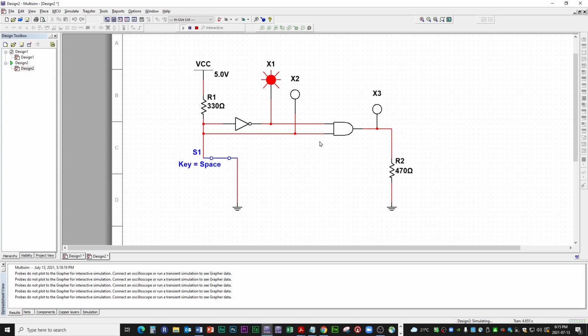Now this other input is directly connected to the switch, which is closed now, pulling everything to the ground, and of course it's going to show low. So here we got high and low, so we got 1, 0 in the AND gate. It's not an invalid state. It's a state of the inputs that is going to produce 0 on the output here.